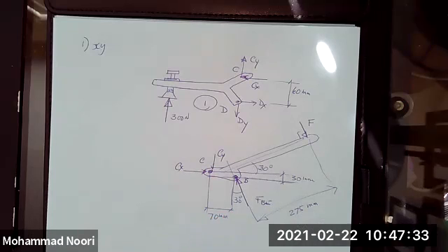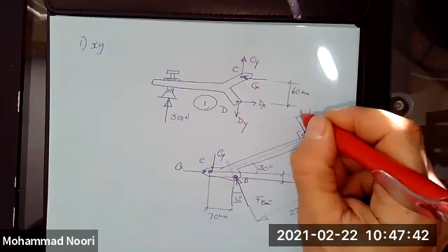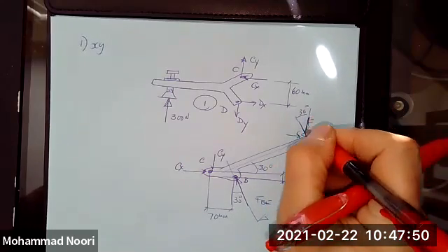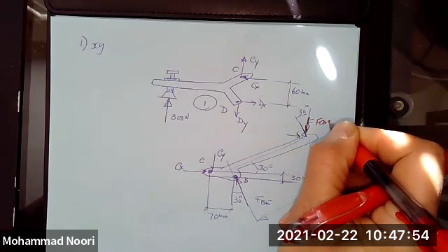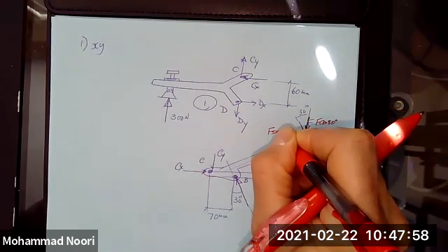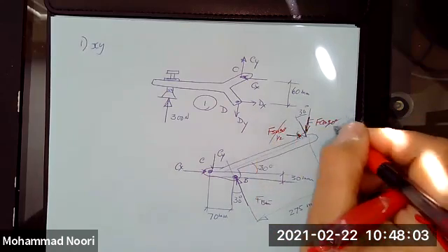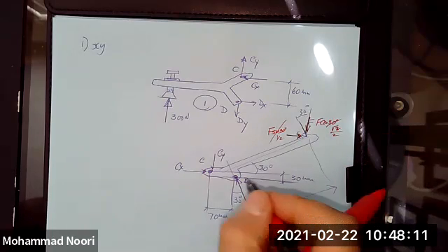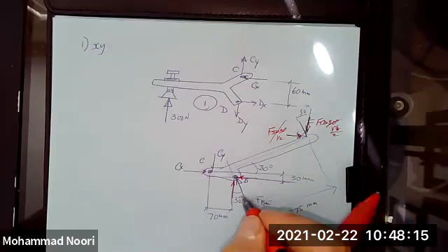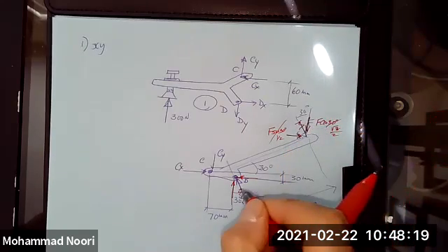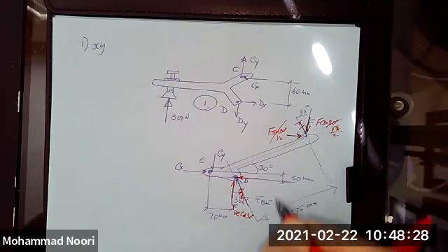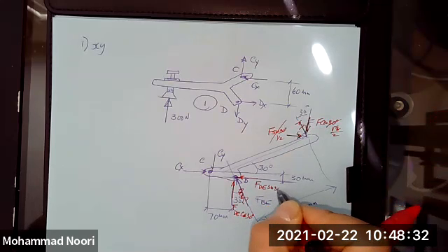All right, so needless to say, you need to resolve these forces into their components, okay? This is 30 degrees given. So you resolve that into its components, okay? You have F cosine 30. This is F sine 30, which is 1/2. This is square root 3 over 2, okay? This one, resolve that, okay? So I resolve that one, I resolve this one. This is FDE cosine 30. This is FDE sine 30.